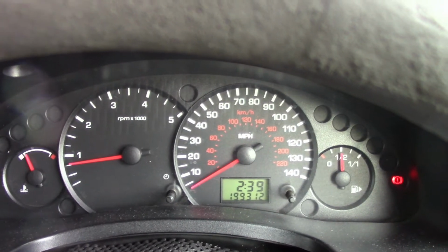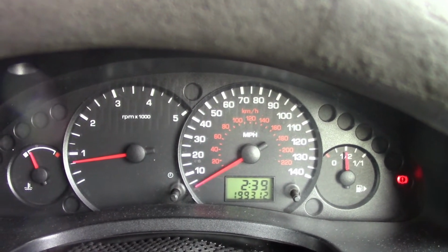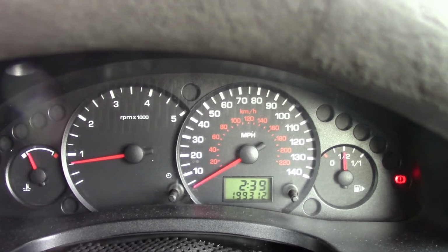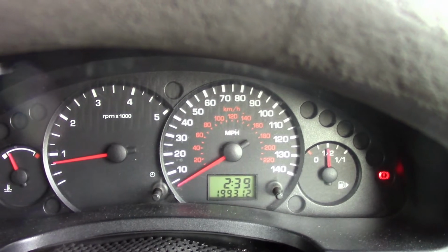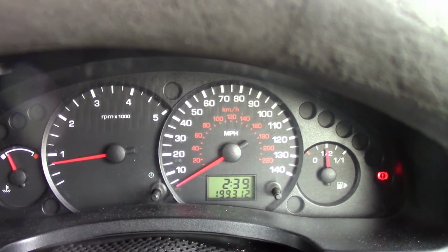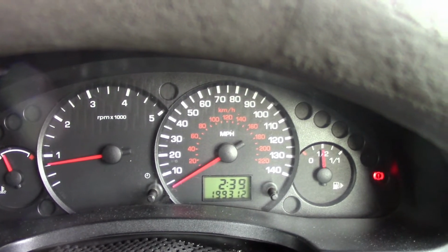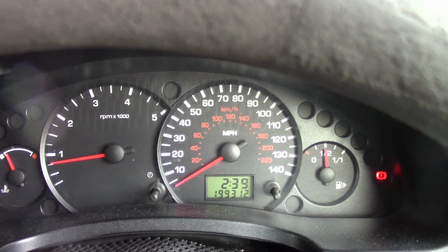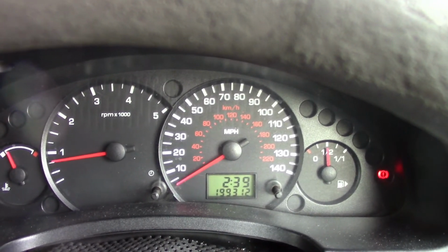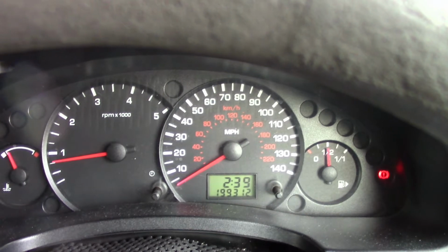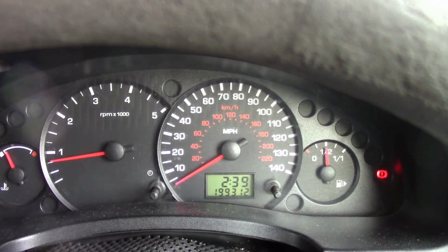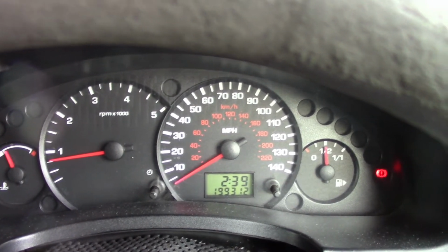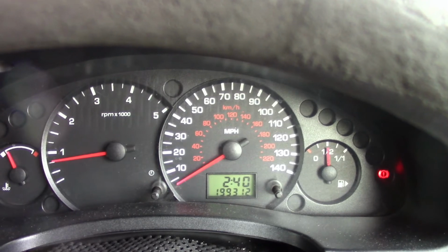And also you saw that the MAP sensor voltage was not changing at all. So I'm going to do some other tests on the vehicle. First I'm going to take the MAP sensor output voltage value. Let's see what output value we will have, and then we will go for further investigation.